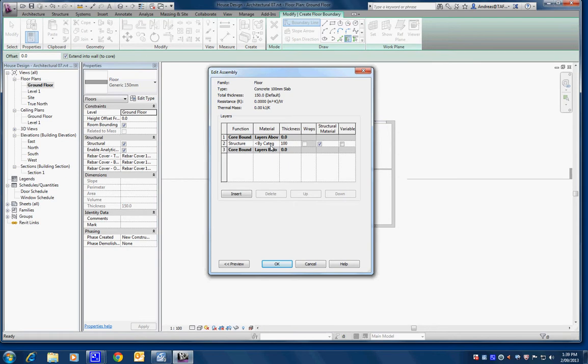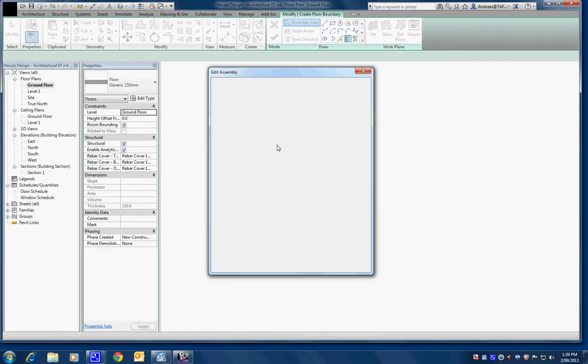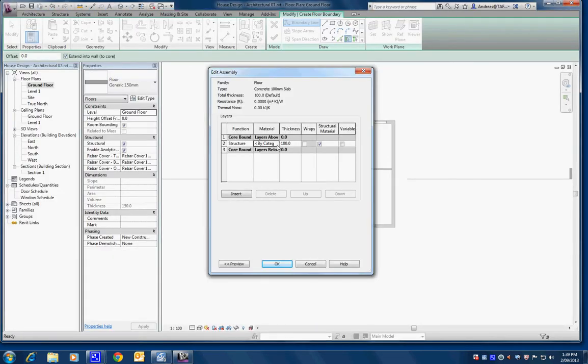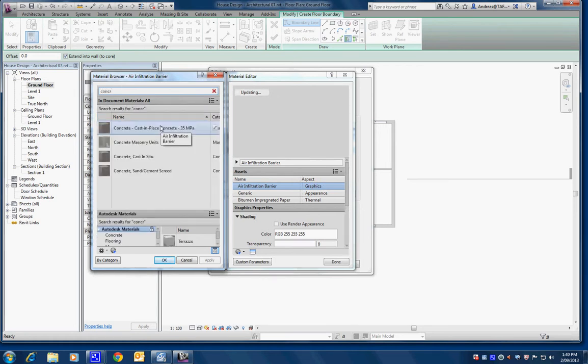Okay. So the other thing is, if we go here, says by category, if we click the little three dots on the side there, we're able to eventually come to an area where we can say what material this is, and we're going to go with concrete, so you can just type it in because there's so much stuff in here. So just start typing it in and this comes up. So let's go with that one there. Alright, and we just go OK.